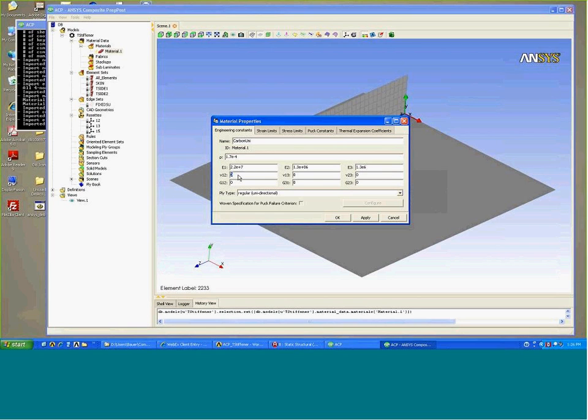Let's go ahead and enter in our Poisson's ratio. So we have 0.32, a matrix dominated Poisson's ratio, and the off axis 0.45. Let's also enter our orthotropic shear modulus for G12. Again, these are just example numbers, and you can enter material information from your data for any engineering database or control database that you may have at your company.